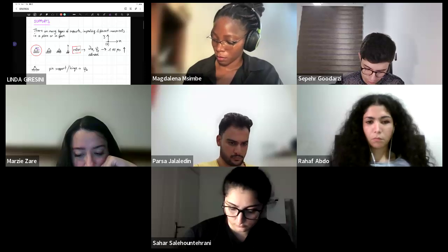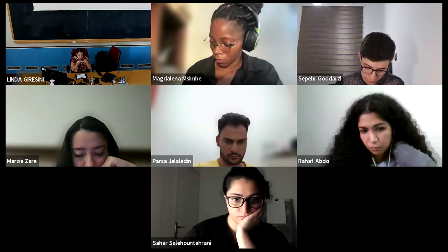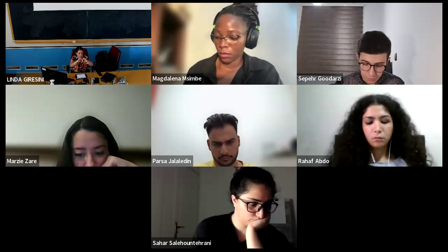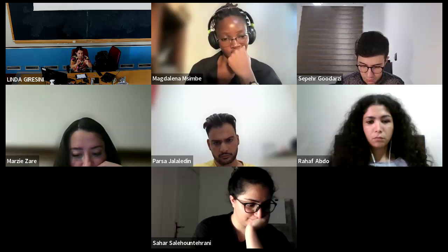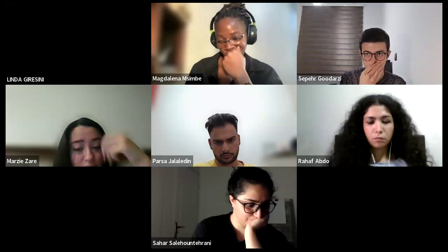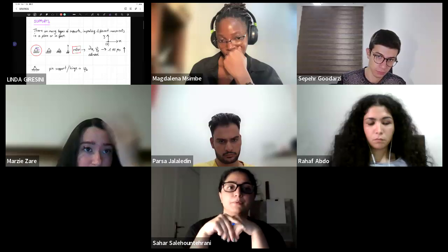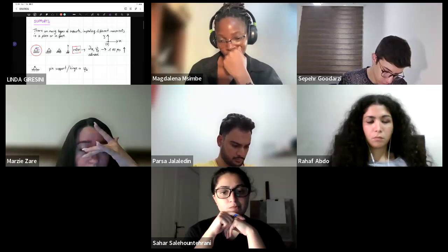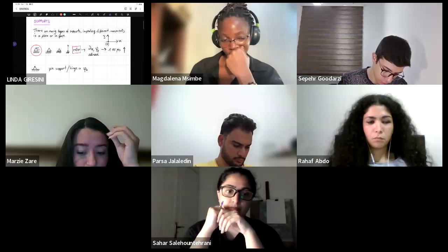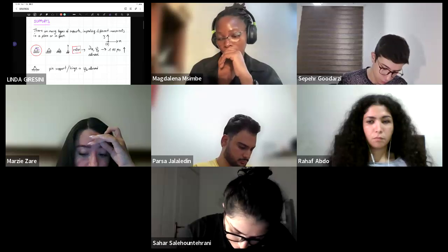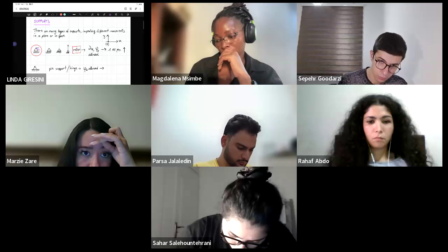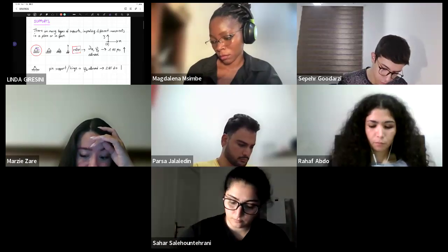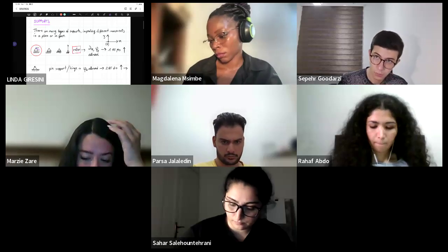So, for example, a hinge is this one. This element is fixed. You have to imagine it fixed on the ground, and the elements connected to it can rotate. So this is a hinge. Okay. So phi z, the rotation, is the only movement allowed. And in this case, we have two reaction forces different from zero. The two reaction forces are vertical reaction force and horizontal reaction force.